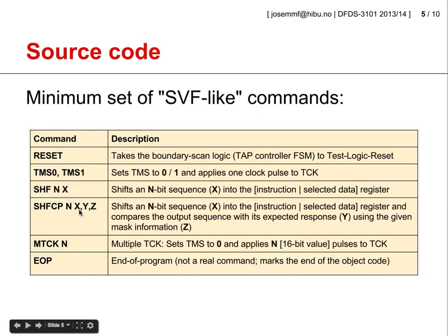In this case, besides shifting a given bit stream X into the board under test, this command will read what comes out and compare it with an expected bit stream given as Y, using another bit stream given as Z, which is used as a mask.